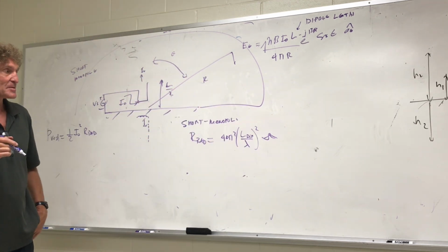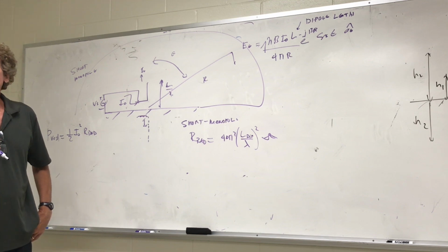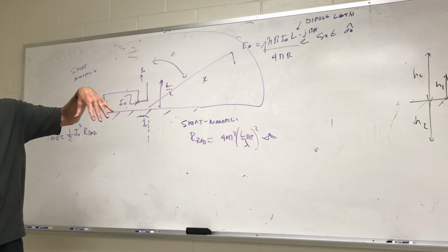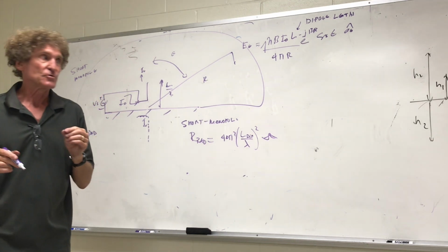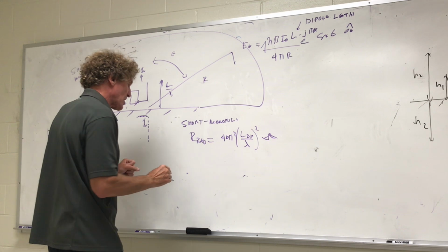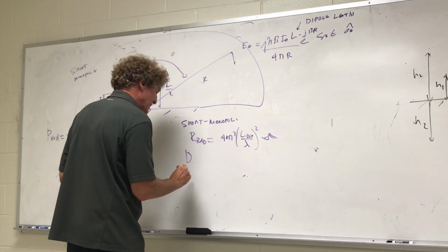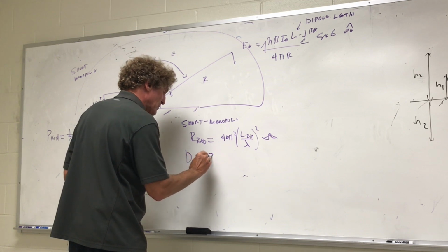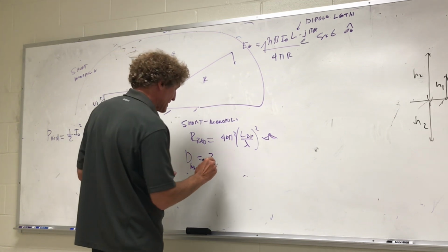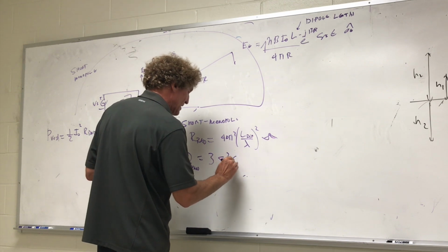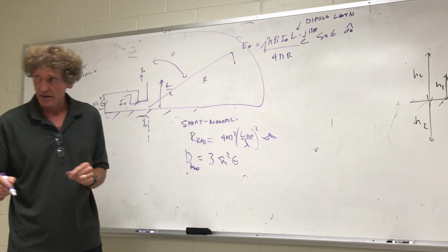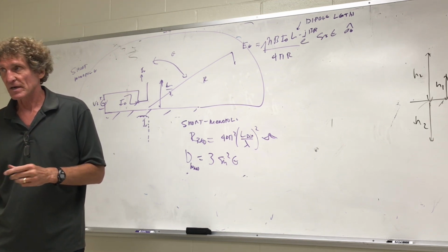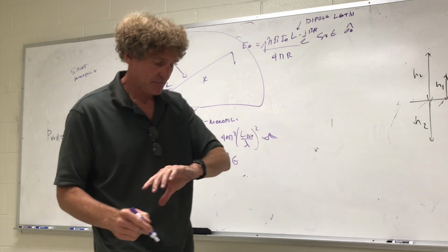Here's another thing that happens because of this. The directivity is doubled. Because the power radiated is only in the upper hemisphere, the actual directivity is doubled. So for a short monopole, D of the monopole is going to be 3, not 1.5, times sine squared of theta. Y'all with me? And that always works. I always try to explain it this way. Sometimes I do a better job than others.